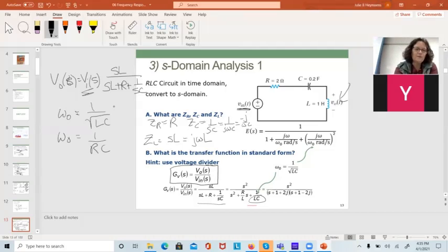If you understand this equation, this is like the key for everything that follows. We're going to get into some semi-complicated terms, but it always is going to come out the same way. For each capacitor, we're going to have another pole. And the pole is going to be C times the equivalent resistance that that capacitor sees. And that always works. Sorry, so in this case, those omega naughts, the top ones are for inductive capacitors and the bottom ones for RC.